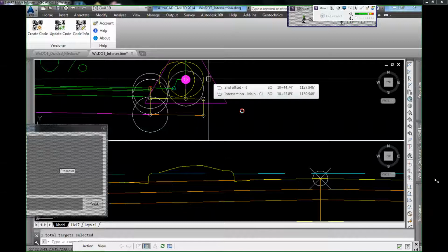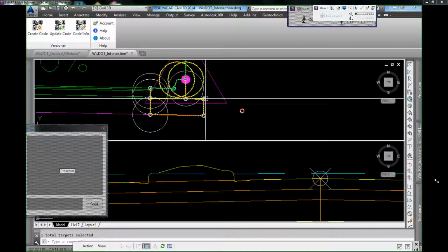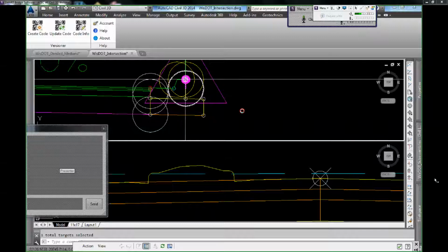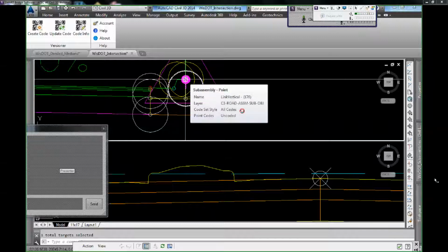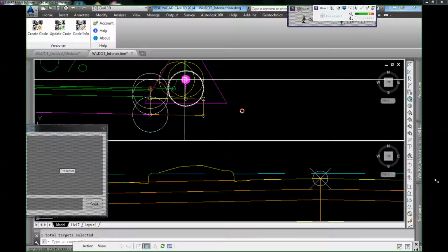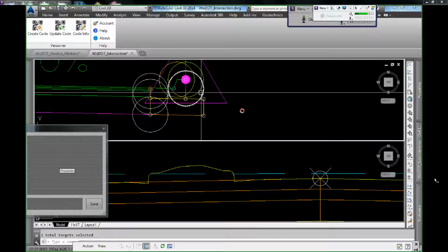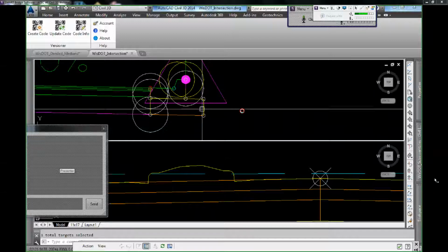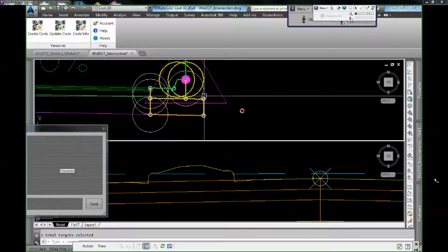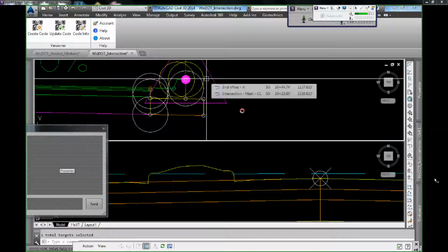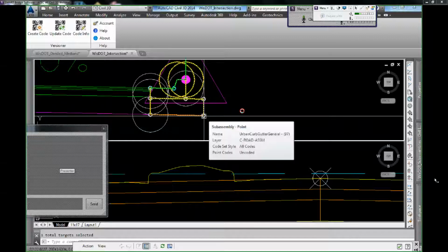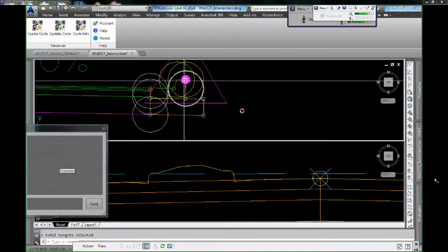Yeah, actually what I would have you do is connect it to the top corridor point or corridor feature line. So that vertical link has a point on the top and a point on the bottom. If you connect the generic link to the top one and then you just put it at the same slope as your terrace, but you put it 1/100 of a foot to the right, then you can use that one.